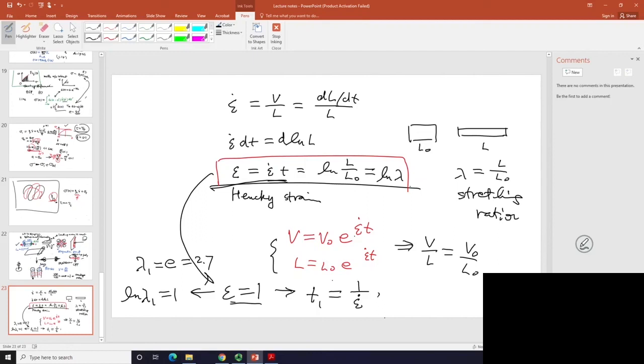Well, it tells you exactly how long it takes. It takes the reciprocal of the rate, or if you like better, L over V. Since we're in the constant Hencky rate limit, that for your convenience, that is also the time you know without even doing an experiment, because that's your initial length versus your initial speed.